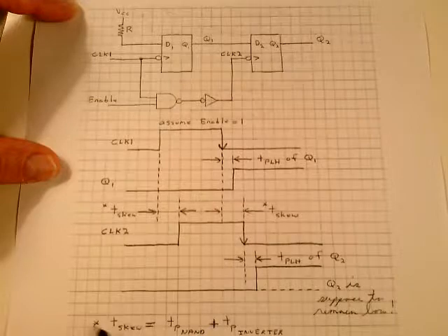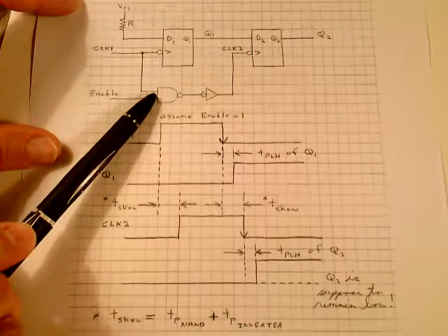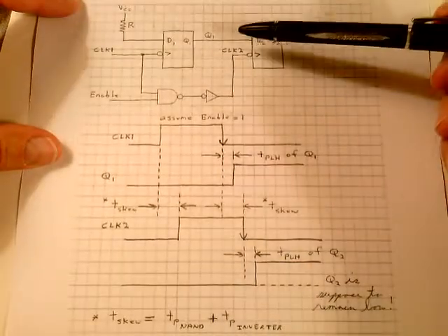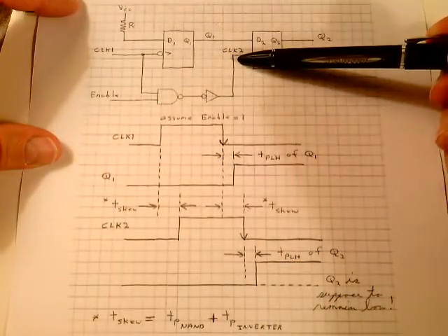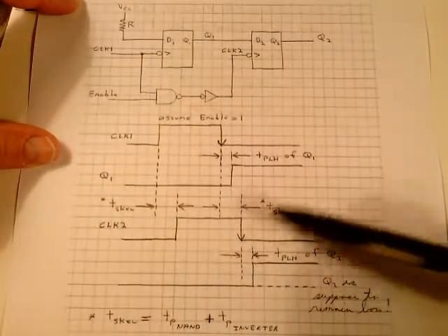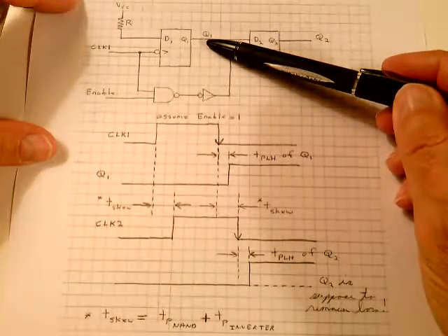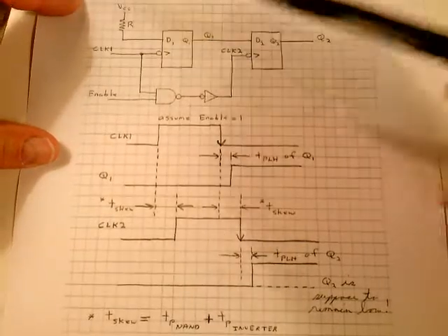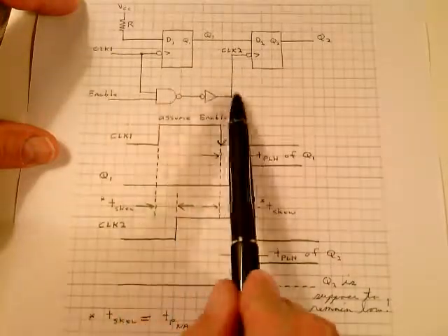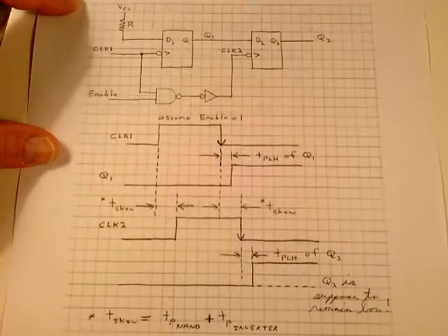The reason there's a clock skew down here at the bottom, you can see, is the propagation time of this NAND gate plus the propagation time of the inverter. So this 1 beats the clock edge here, and this output Q2 goes to a 1, all because of that clock skew. We have to slow this signal down up here. We can't let Q1 get set up and then, sometime later, because of this clock skew, this negative edge on this clock finally makes it out here and sees that 1, and this goes to a 1 during the same clock period.